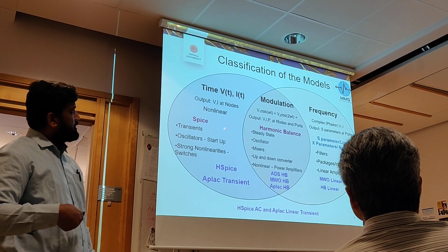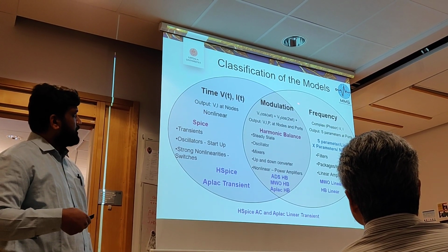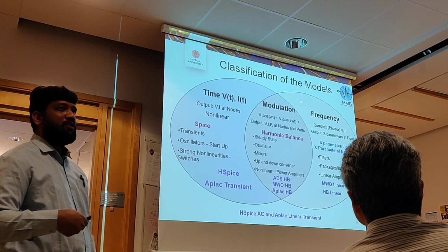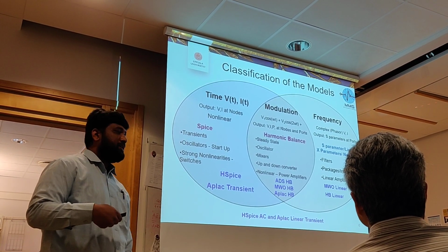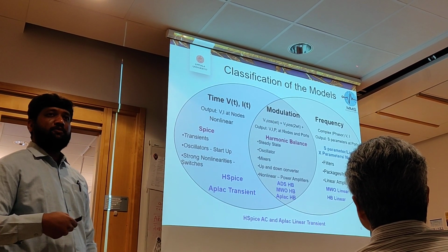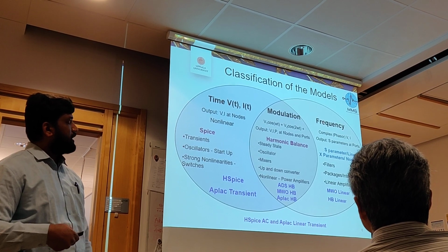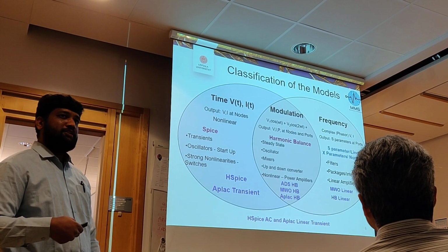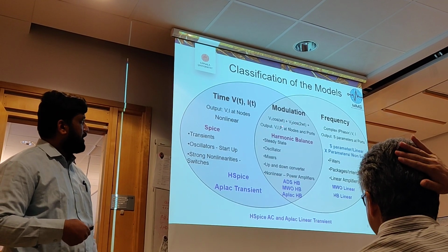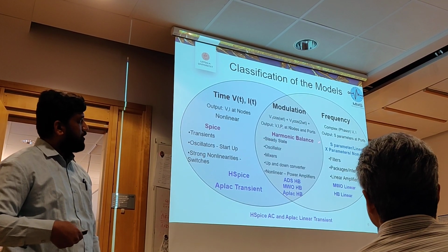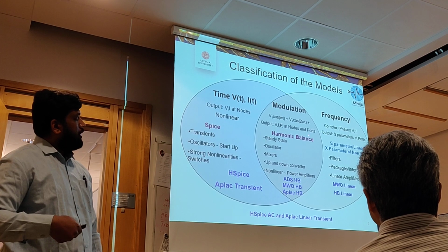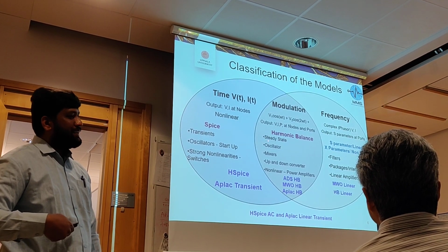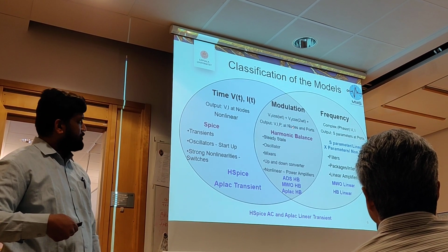And cumulatively, there is a common between time and frequency domain: there is a modulation. If you look at the modulation schemes of any communication system, you will end up with a lot of exponential or trigonometric equations where we need to take care of a lot of harmonics, intermodulation effects, and a lot of nonlinear effects. For that, we have harmonic balance methods. Models are available. Basically, it is like steady state numerical analysis.